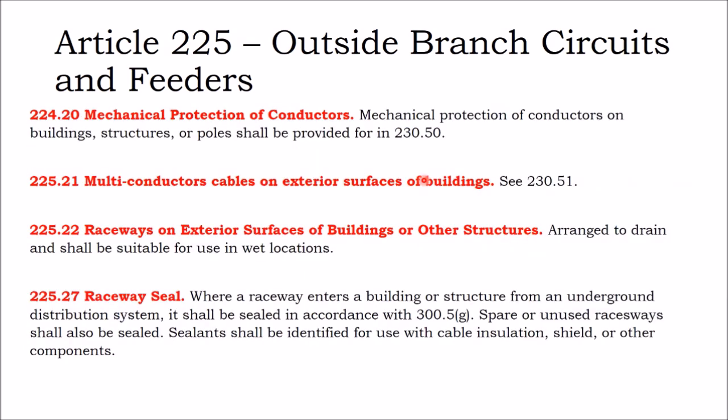And so if you're at the very top of the building, you can just stay to the side of the building and go over the top. So, essentially, you have to be 3 feet away from all objects, except there's an assumption that you're going to stay on the same plane of the building, and the very top is what's considered out of harm's way. Of course, again, minimum safety standards. So if you have a rooftop porch or whatnot, going over the top of the building would not be as safe as, say, going back into the building.